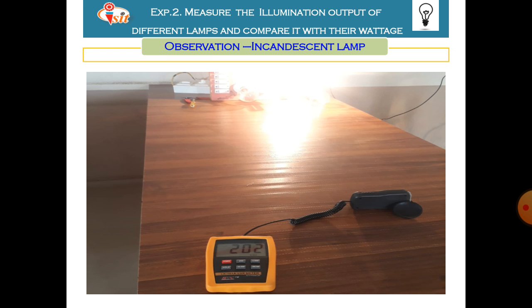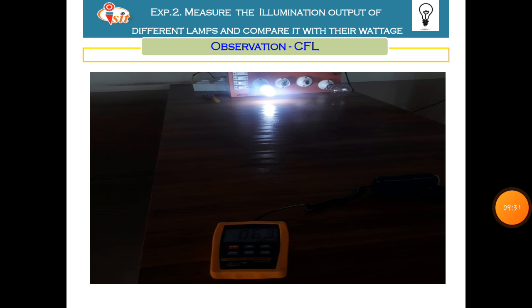Now the readings. When we kept the lux meter light receiver 1 meter away from the incandescent lamp, it measured the lux level, that is 202 lux. Here the lux meter is kept for the CFL, 1 meter away, and it gives a reading of 63 lux level of illumination.